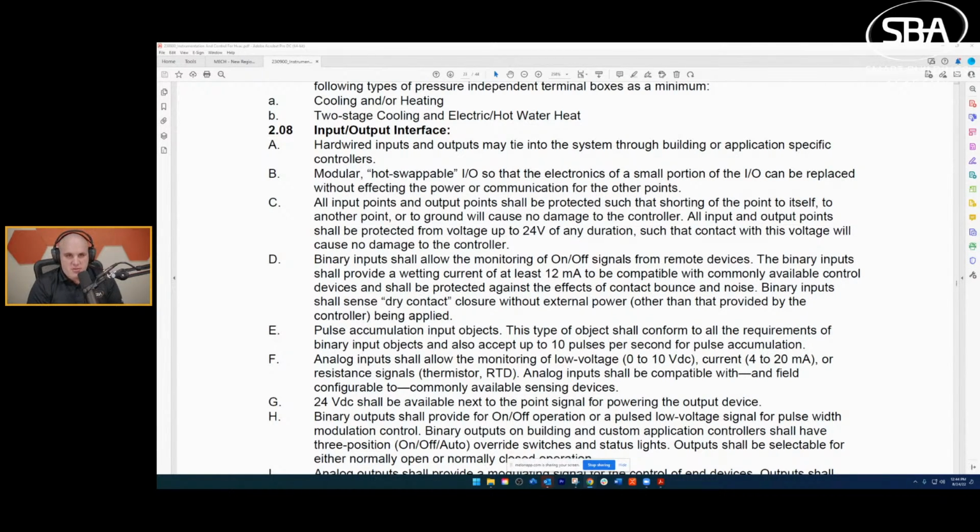General conditions also cover things like liquidated damages, which, even in some cases, delays out of your control, you still need to execute. So, hey, it rained for a month and they didn't get power up because they couldn't pour the slab. Well, that doesn't matter. You still need to be able to hit the schedule so they can get the certificate of occupancy. So those are things that you should be really cognizant of. Thanks for bringing that up. Thanks, Eric. I appreciate it.